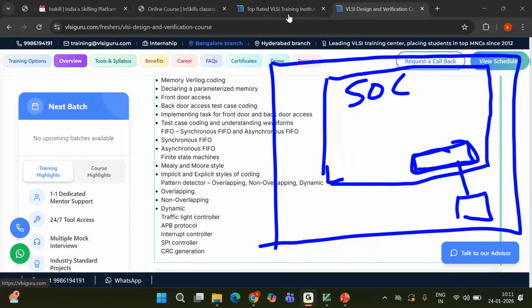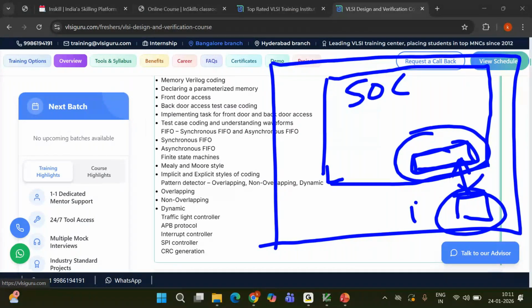So communication between the fingerprint sensor and the chip will happen with respect to something called peripheral controllers, peripheral protocols. An example is the SPI protocol. SPI, I2C are examples. Is it clear? Ethernet is an example. So you will learn regarding the SPI protocol in this.